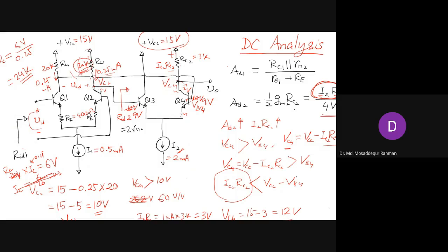And you see that we have taken an input voltage of 10 millivolt. But we can have an input voltage of a maximum of 20 millivolt for a differential amplifier because of the two transistors. And if the input is 20 millivolt, then you see the output will be even double, right? Now we are having 2.6, and that will multiply by 4. So it will be even more than 5 volt. So if the maximum input is 10 millivolt, then this circuit will work fine. But if the input is even higher, then this will again fail, right?